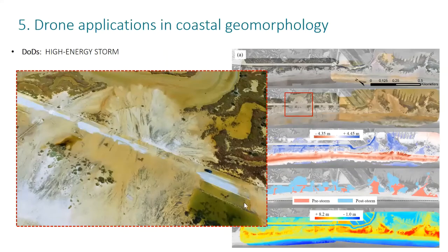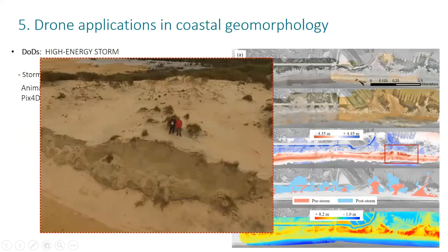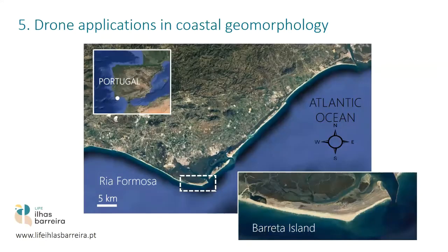And for you to see, having a mosaic of this area with high resolution allows us to really measure with accuracy not only the area of the deposited material, but also all the volumes. And for example, we could see that the vertical erosion that the DEM difference was giving us in this area was of 5 meters or something, and it correlates with what we saw in the field. As you can see, this certainly is 4 meters. So we really map changes with high accuracy, and with other remote sensing methods, we weren't able to do that, or at least not at a reasonable price.